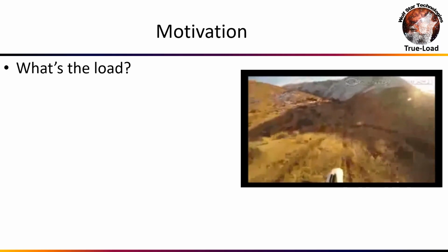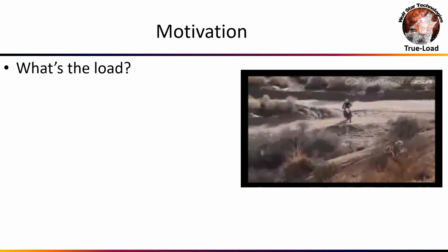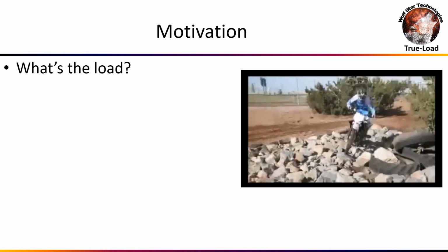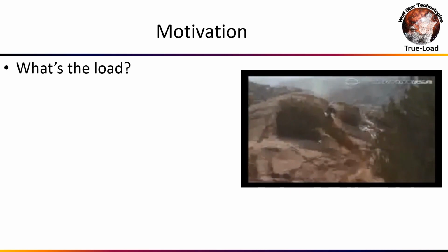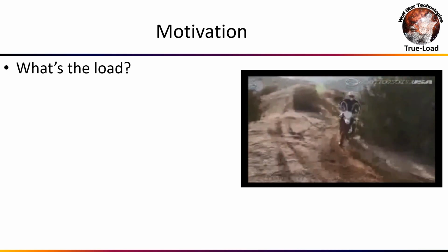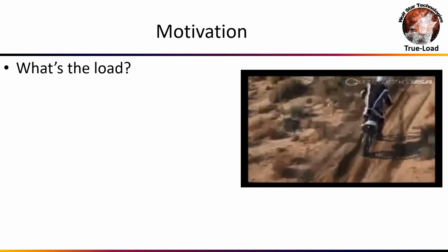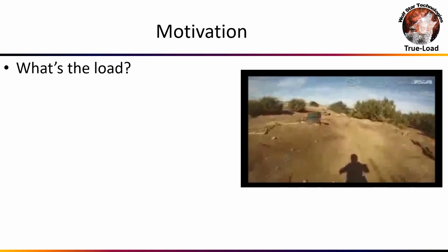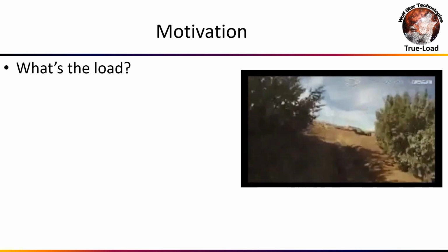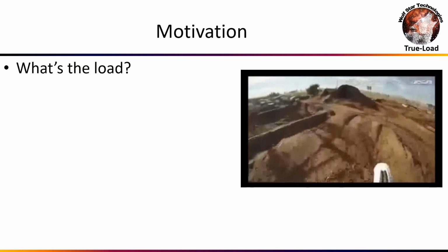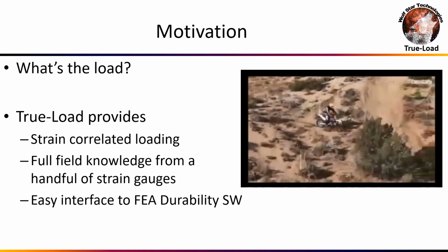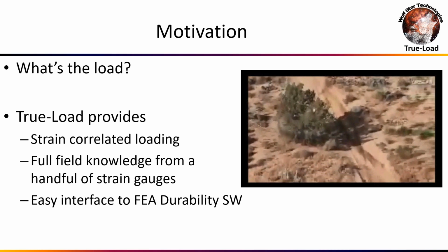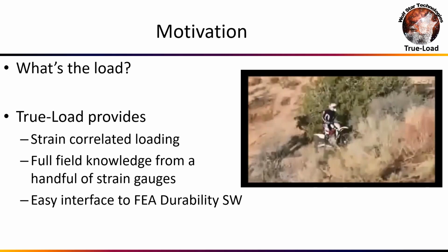What do we do? Well, we recognize the individual components of the motorcycle are basically responding linearly. So we'll target the swing arm, the frame, the crankcase, the handlebars, the gas tank, the fenders, the luggage systems. We'll put strain gauges on these subsystems and let these subsystems become their own load transducers to measure the operating loads on the structures. And then we'll use those loads to back calculate the loads in the subsystems, and you can use those loads then to do design and optimization.